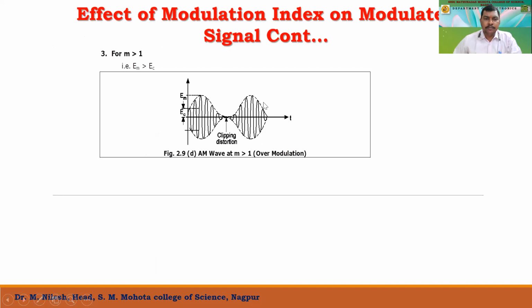Yes, exactly, it is clipping distortion because we will not have the negative half, which is to be modulated. And we call this over modulation. The peak will be highest and here it will be 0.